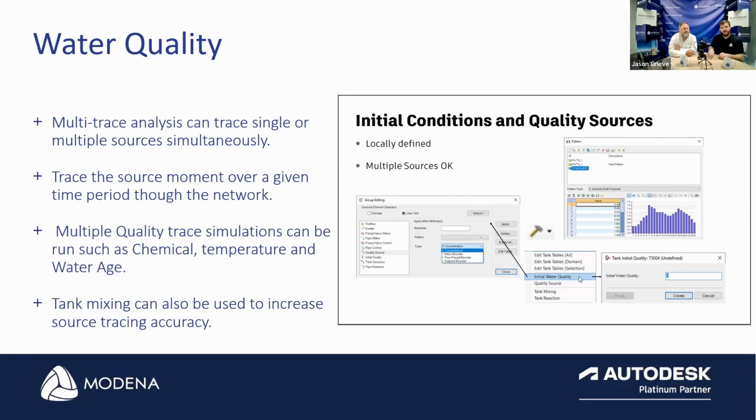If we back engineer that, then we'll be able to trace that to the source. We can even see that movement live within our network. So if we see that for some reason we don't have flow down the main line, but we have a diverging flow, what can be causing that, and why are we getting that divergent flow rather than what we are expecting to see?